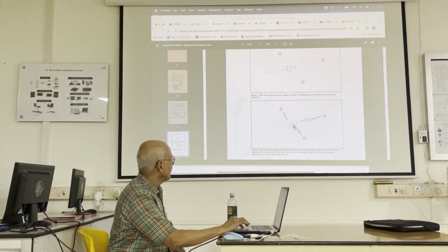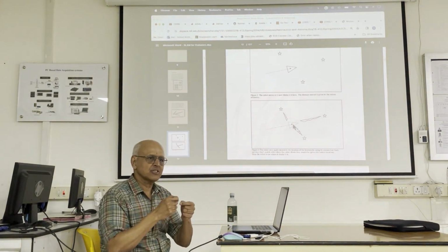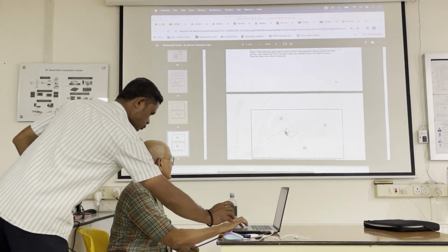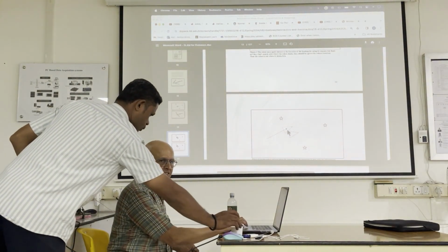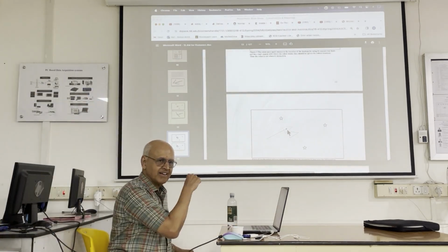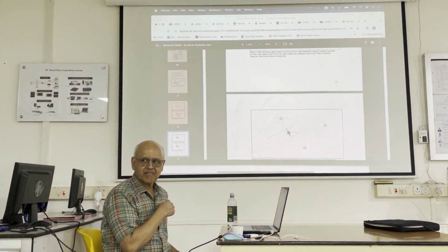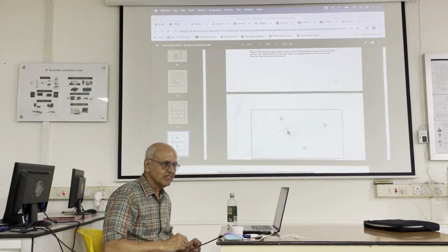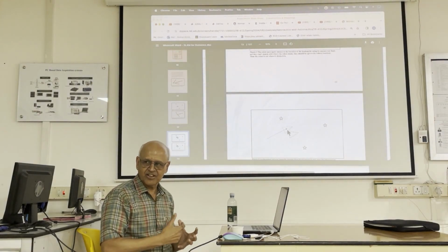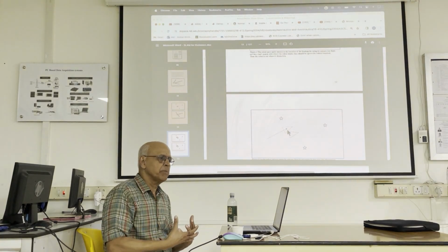So you have to resolve the two together. That's what SLAM is. There it is. The robot is actually here. Odometry is telling you this, but you're actually here by the LiDAR measurements. Now, do you go with both positions? Do you average two positions? No. There's a technique known as Kalman filtering, which finds the best compromise.